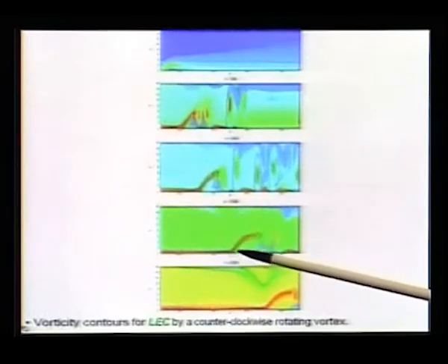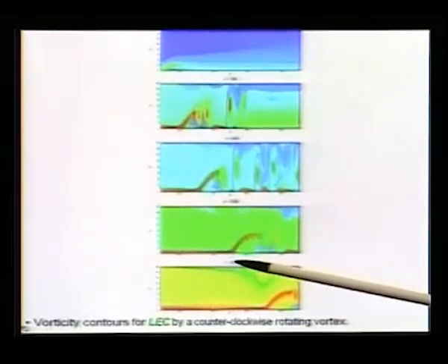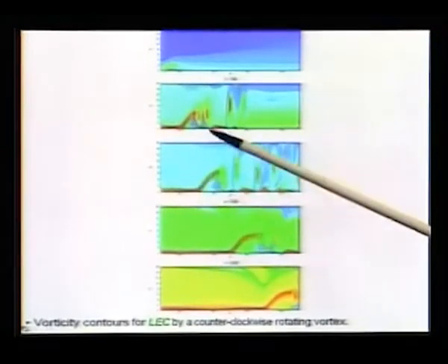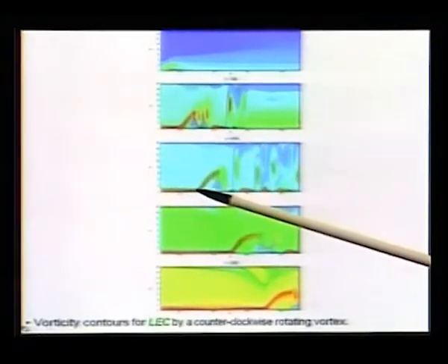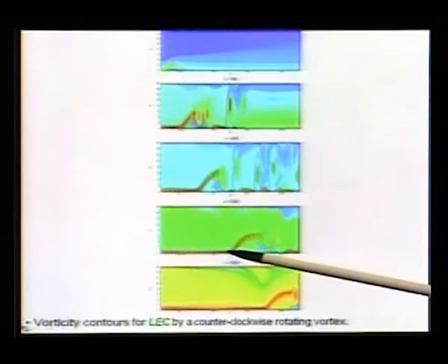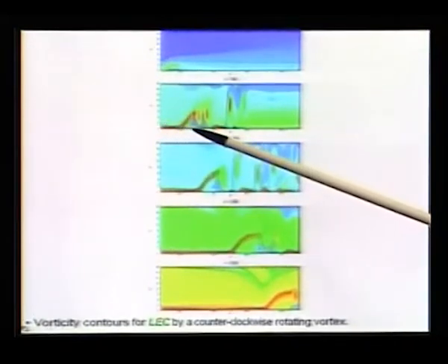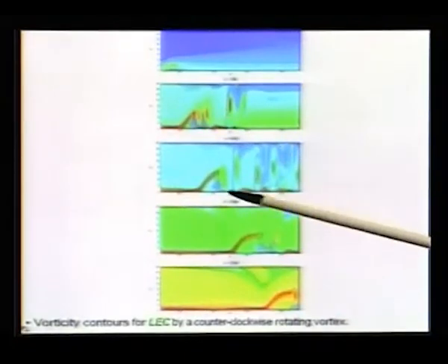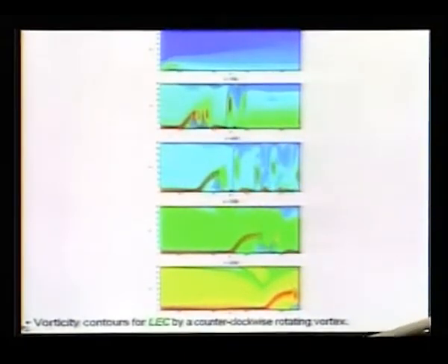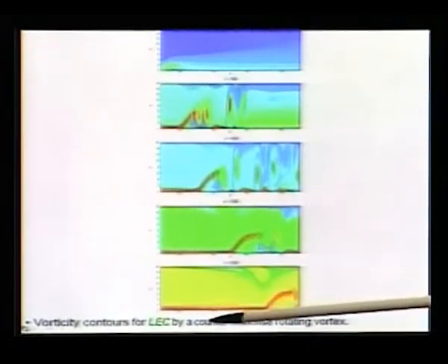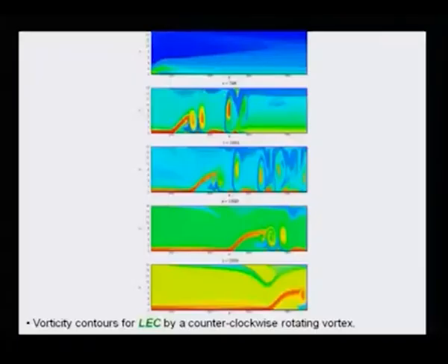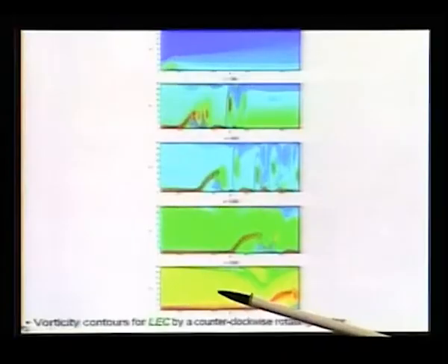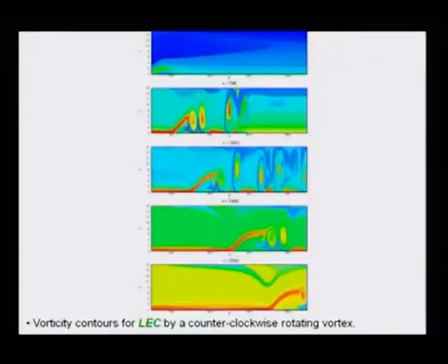Here it was getting affected. Here also you could see the vortex is somewhere here, there is a little bit of thinning down, and here you can see it has thinned down a little more, and here the thinning down is marginal. But as time progresses, you can see this is the trace of the free stream vortex. That is why we did not even mark it by an arrow. But here in this part of the shear layer, it has acted over a longer period, and that cumulative effect shows a significant thinning down of the boundary layer.